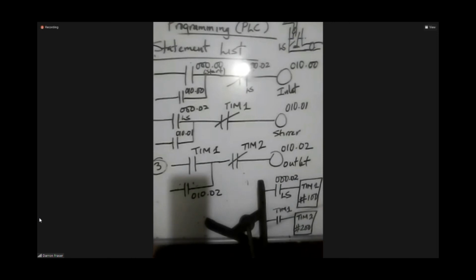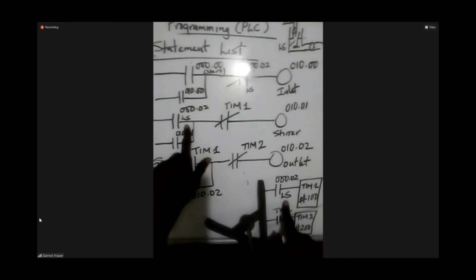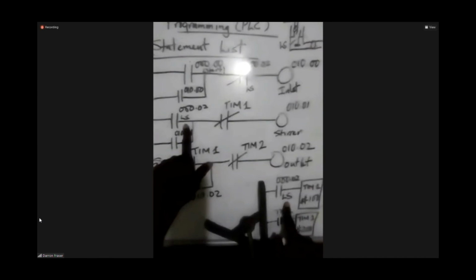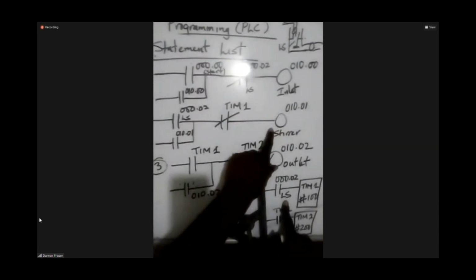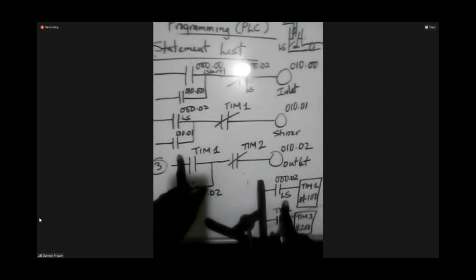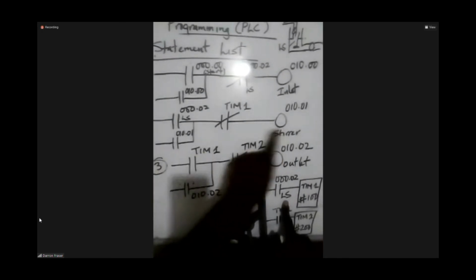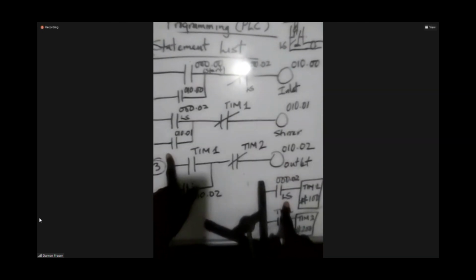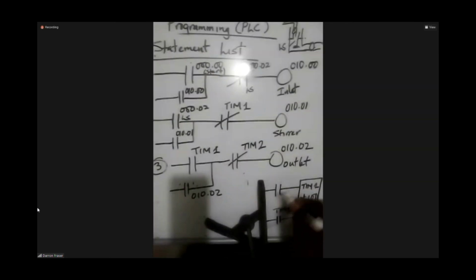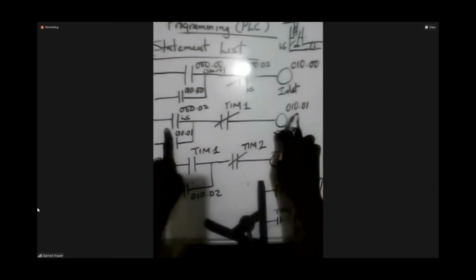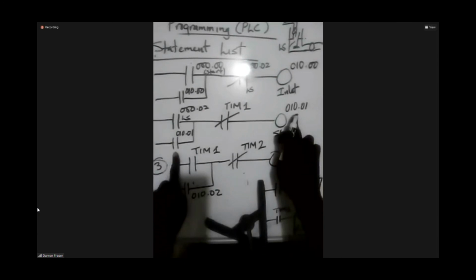So let me tell you what the fix is for this. The level switch is not behaving, but the reason why the stirrer doesn't have a problem is because we latch it. So once the stirrer turns on, it stays steadfast in that motion. So the level switch turns on the stirrer, because this is also turning on the timer. I mean turning on the stirrer.